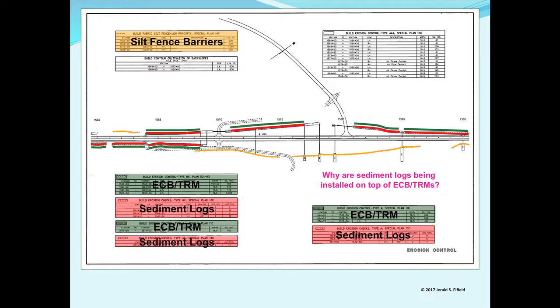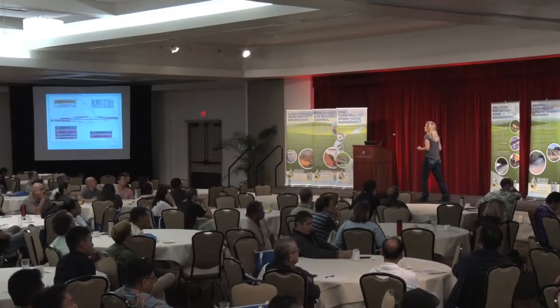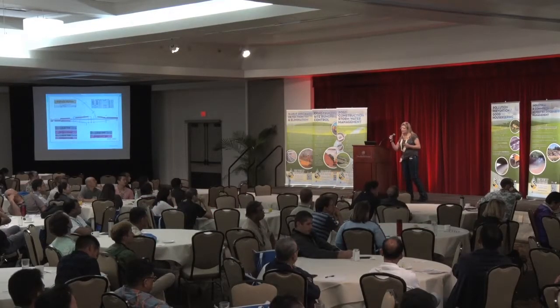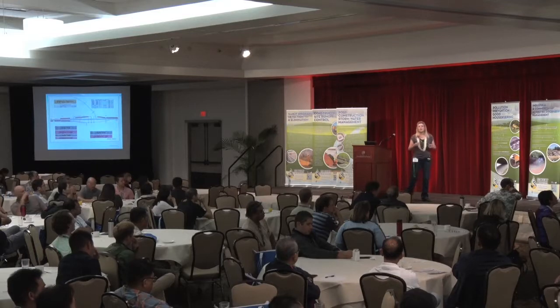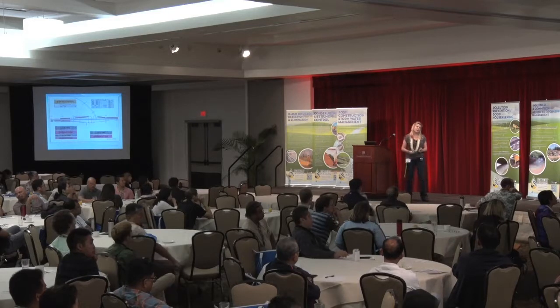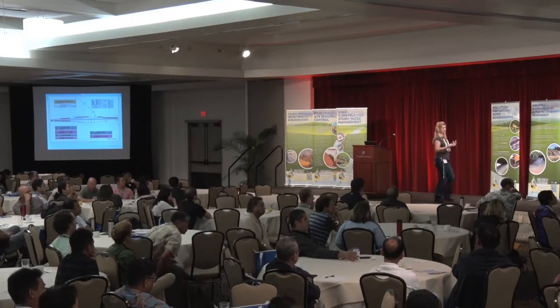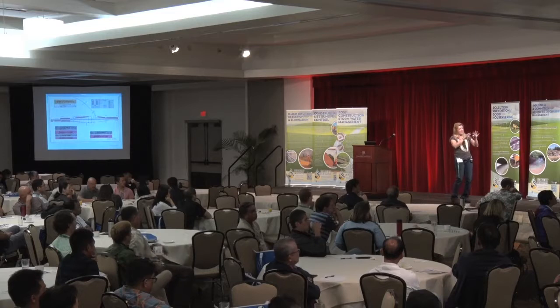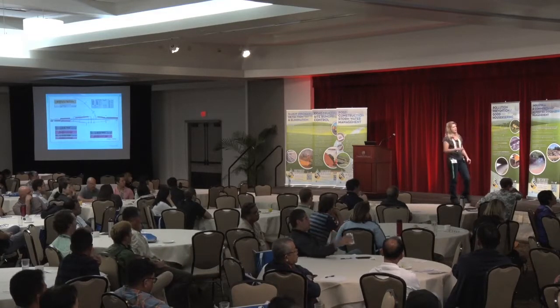Okay, I actually give them credit because they're utilizing a BMP that is good at controlling erosion. They're not just leaving these channels open and saying vegetation will take effect. They're actually putting a blanket of some kind in there to help reduce the erosion aspect of it. I give them that credit. Of course, my question to them was, especially if they're using TRMs, the fact that they're in a swale, did they do the proper calculations to determine the right blankets? Something that I would be checking to see if they have those calculations available. But that aside, that's a whole other topic in and of itself.